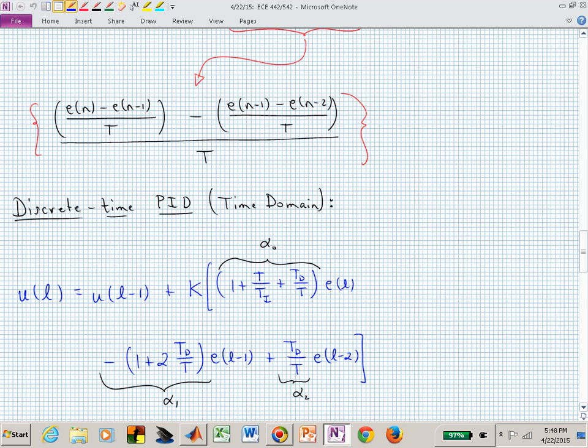But I'm going to get lazy and say I don't want to keep writing all of those parameters. But if you were designing a PID controller, and maybe you did it in the analog setting, you now have an integral time, a gain, and a derivative time. Once you have the sample period, now you can implement that with a difference equation, because you have all of these coefficients in this difference equation that's realizing the PID controller.